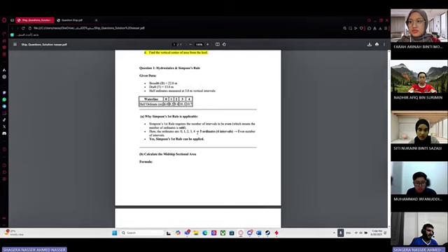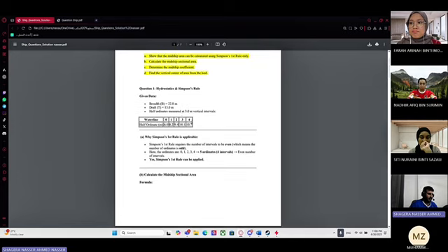As shown, the ordinates are 0, 1, 2, 3 and 4. So 5 ordinates, which means 4 intervals, so an even number of intervals. That means for part A, yes, Simpson's first rule can be applied for this question.